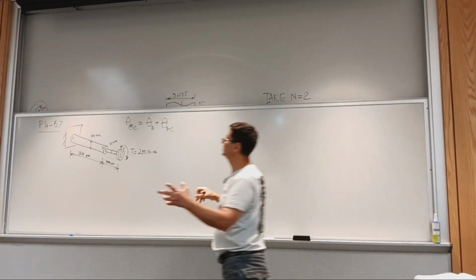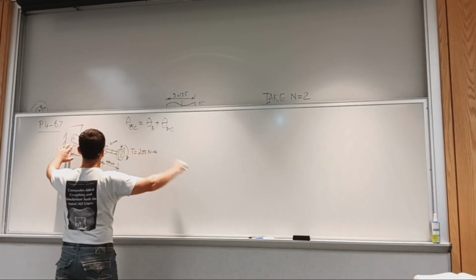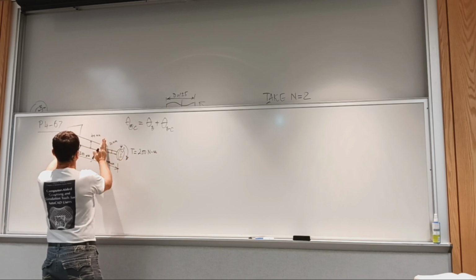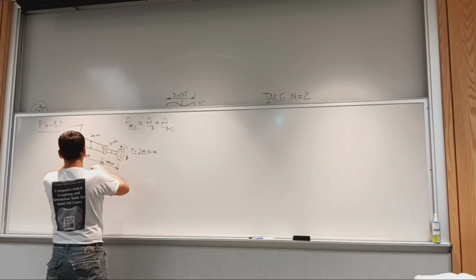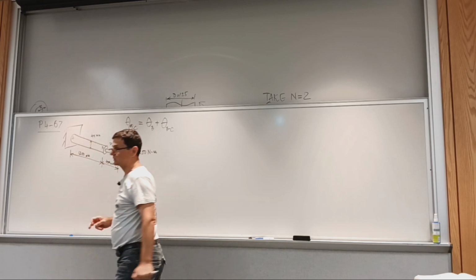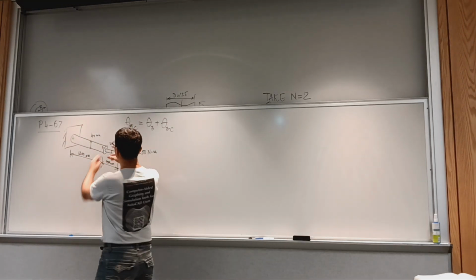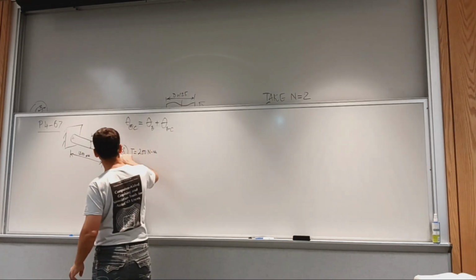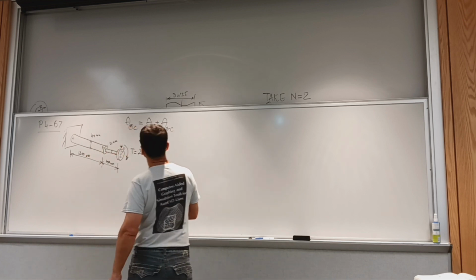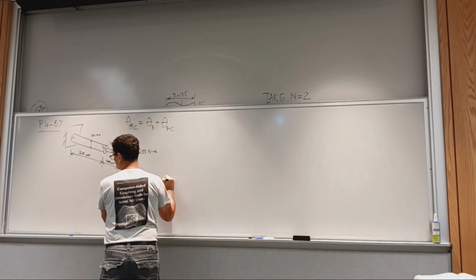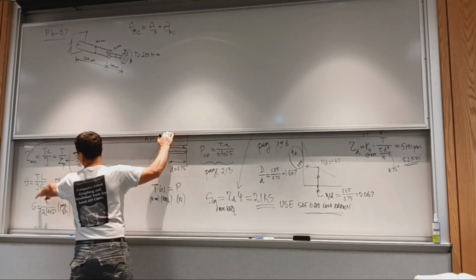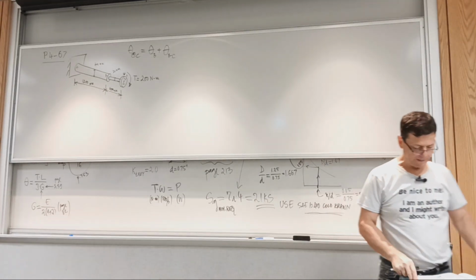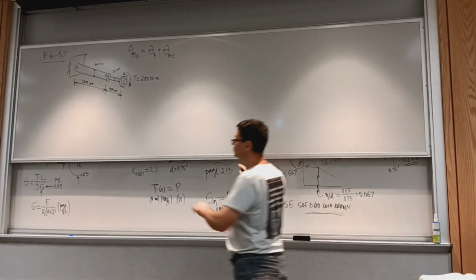Same as with tension. We solved the problem with tension. If instead you pull the free end C, you have a stretch of portion AB, which is one thing because we have a bigger diameter, and then there's the thinner portion that will stretch, and you add the two to report a total displacement of point C in the direction of the force. But here it's torsion. And we had the equation for the angle of twist in radians. So let's see what we need.